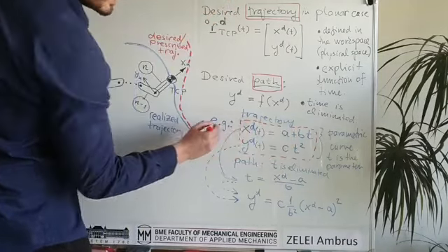Which only exists virtually, so this is not a physical space. And we see that this is infinitely large, but after having a whole rotation of Q1, for example, it doesn't matter if we have further rotation. So we can have this range of minus pi to pi for Q1, and also from minus pi to pi in the other dimension, which is Q2. So this whole range can be reached by the robot.